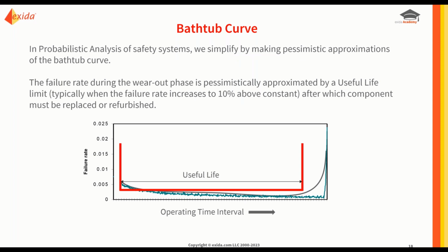In functional safety, we need to know the useful life, because when the useful life ends is when the failure rate goes way up. When the dangerous failure rate goes up, the risk reduction that we need in a safety system will not be there. Risk reduction factors will actually drop. So it's a real bad idea to run devices that are part of a safety function to failure.